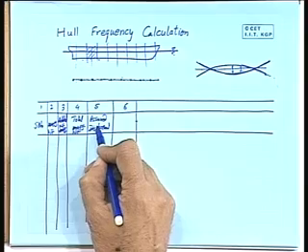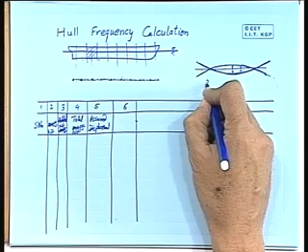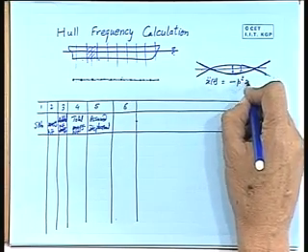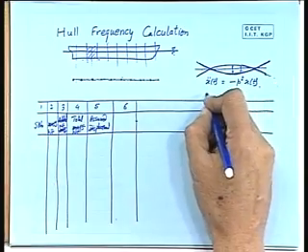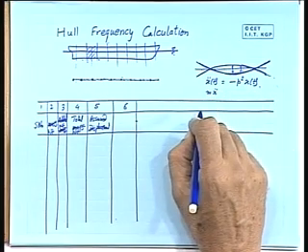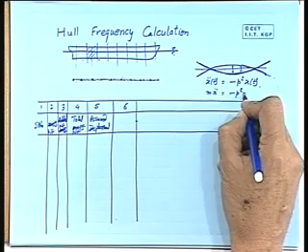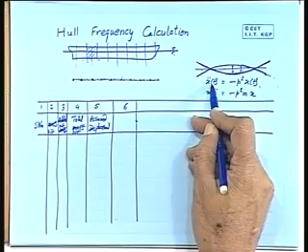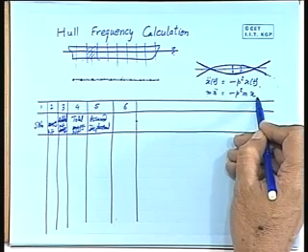Then total weight into the assumed displacement, because I assume harmonic motion, and therefore x double dot of t is given by minus p square x of t. Okay, and m x double dot is the inertia force. So if p square x is equal to x double dot, then inertia force is equal to minus p square m x.